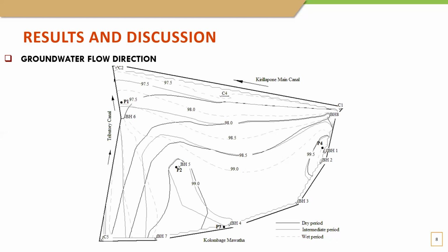This depth does not meet the 2.5 requirement, as I discussed in the previous slide, stipulated in the standard SLS 745:2004. During the dry weather period, the said requirement was observed; borehole 6 and borehole 8, located near the canal, are in good condition.